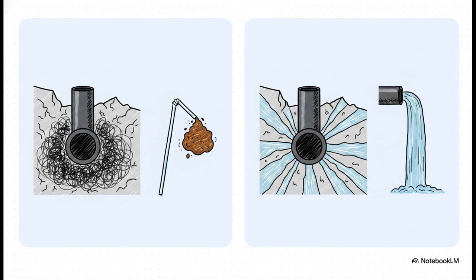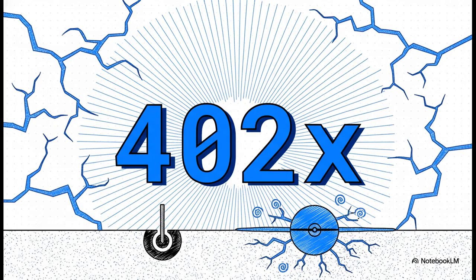Conversely, engineers actively try to achieve a negative skin effect through a process called matrix stimulation, like pumping acid down the well. By dissolving those rock blockages, they might achieve a skin effect of -2, which effectively multiplies the well's radius by 7.4 times. And this brings up an absolutely mind-blowing number that illustrates the math behind hydraulic fracturing. When engineers artificially induce fractures in the rock, they can achieve a skin effect of -6.